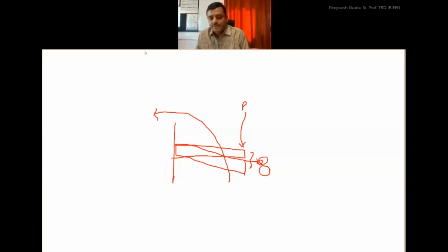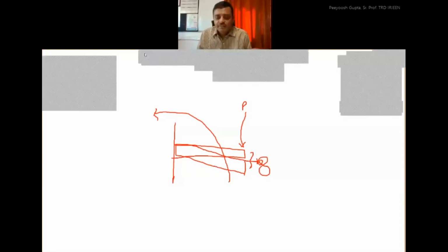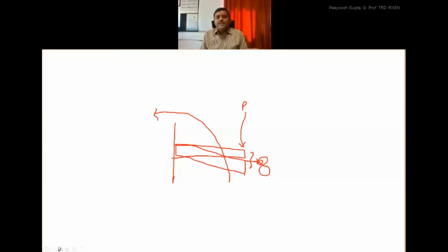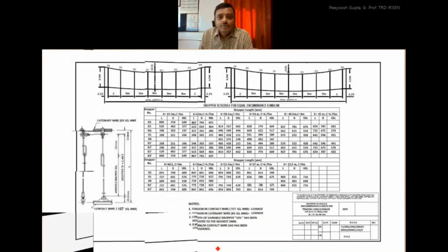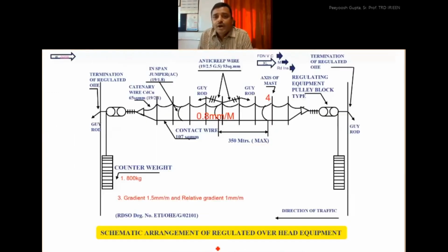The bending moment capacity of various masts is known to us: BFB has 4011 kg meter, RSJ is 6674 kg meter, B150 5053, B200 9140, B250 14008. So we know the bending moment, and with that we can calculate whether the mast is suitable or not.